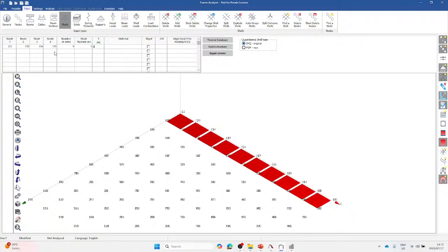And I'm going to make the thickness of the slab 0.3. And in terms of material, I will use concrete 30 MPa. We can use 40 MPa, but this is just for modeling practice for today's webinar.